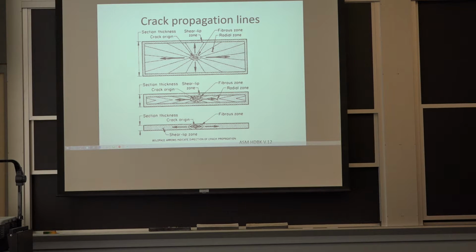Now, on an axle or anything that is really vibration load, it's almost impossible because you start getting millions and millions of cycles very, very quickly. So if you expect millions and millions and millions of cycles, 100 million, you don't want a crack to start. If you only have up to 200,000 cycles, you can have a design where you say, you know what, it's not great to begin with, but I don't want that crack to grow beyond a certain limit before the service life. Are there materials known for being crack resistant or propagation resistant?